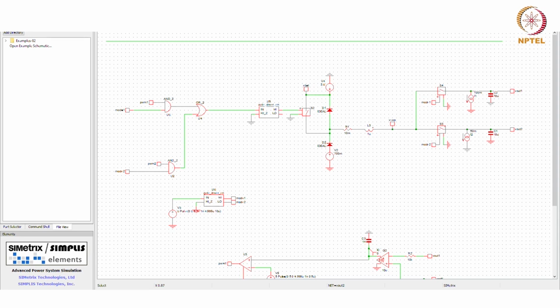So you have to take care of that, and that is usually taken care of by making sure that whatever current is supplied here, you have to supply that here too. So that balance you have to maintain. If there is extra current, you have to throw it out by adding a freewheeling switch here actually. So discontinuity is always there. You cannot say that the V out equals D times V in formula is gone completely because of these switches.